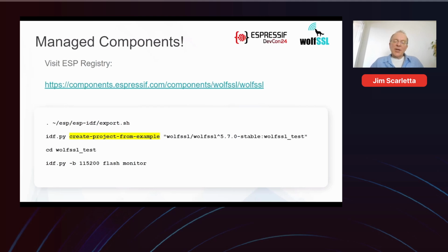So yeah, the only catch there is make sure you probably want to specify a COM port. It'll look for the first COM port available. So if you have several, you might want to add the -p for the port, the COM port.